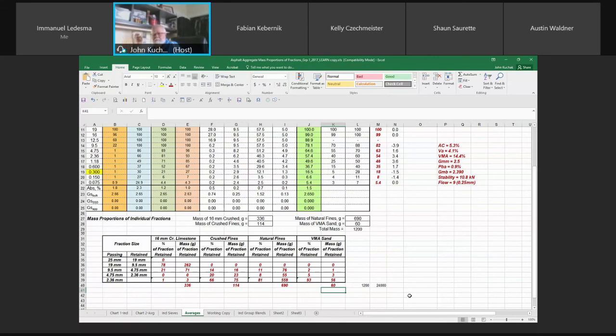One question was: why do we water or moisten the granular base immediately before we're paving? So many people say two reasons, and I only gave one mark. They say, for compaction purposes and to prevent the base from sucking the water out of the concrete, which is the right answer. Because I said immediately before, if you're paving, compaction's been approved.